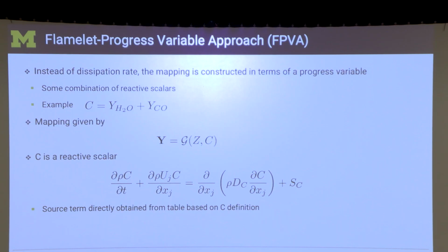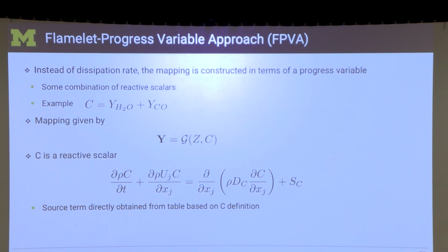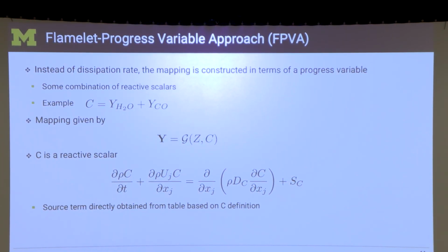This is the flamelet progress variable approach. So this is the extension of what I just showed you. It does something a little bit more here. We found out that if you have extinction, locally, if the flame extinguishes and comes back up, there's no way to describe it using that strain model that we had. So this fixes that problem. It's called the flamelet progress variable approach. It's very popular. It's pretty much routinely used for most aircraft calculations. This is a good technique to use.